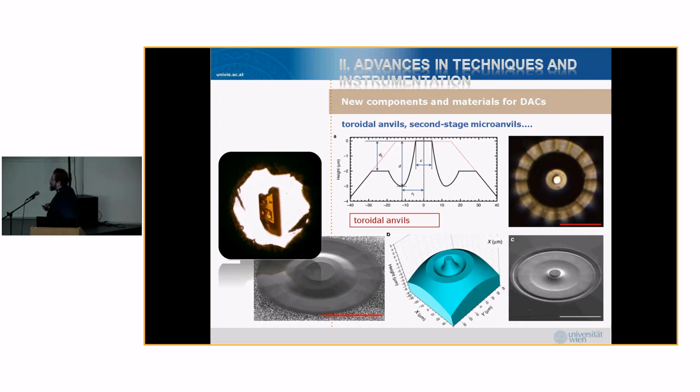and make this kind of structures that you see here, with a top part which, in cross-section, looks basically like having an anvil sitting on an anvil. So you have a kind of double stage system. You will see a proper double stage system anyway, and with these so-called toroidal anvils, because you leave out these toroidal excavations here, it is really better to go in the central part to get to higher pressures, and in this case to reduce the strain that you produce on your anvil.